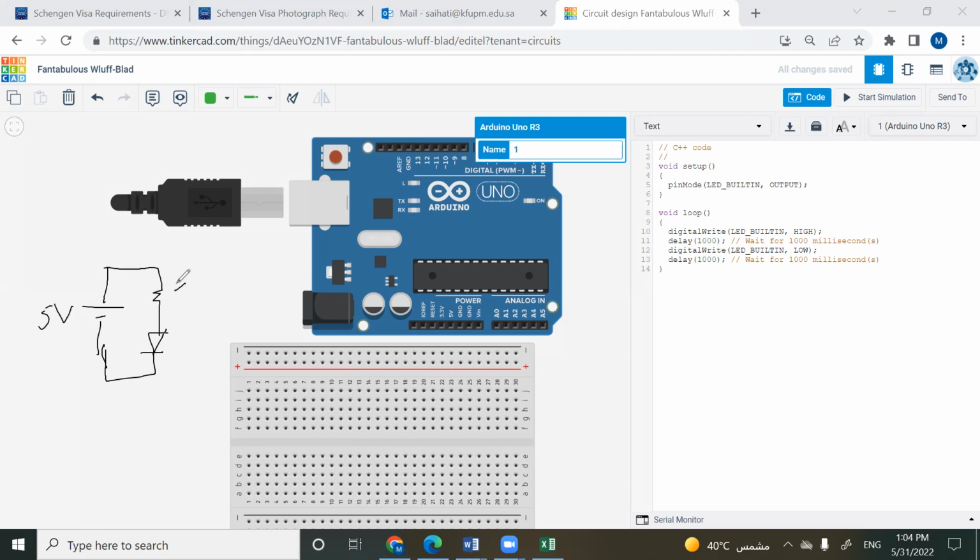This one could be any range of values, but for the Arduino, we want this to be using the least power possible. So to make the power less, we have to increase the resistor, right? You know that, for example, V squared over R is equal to P, right? This is the power. So the larger the resistor, the lower the power, right?